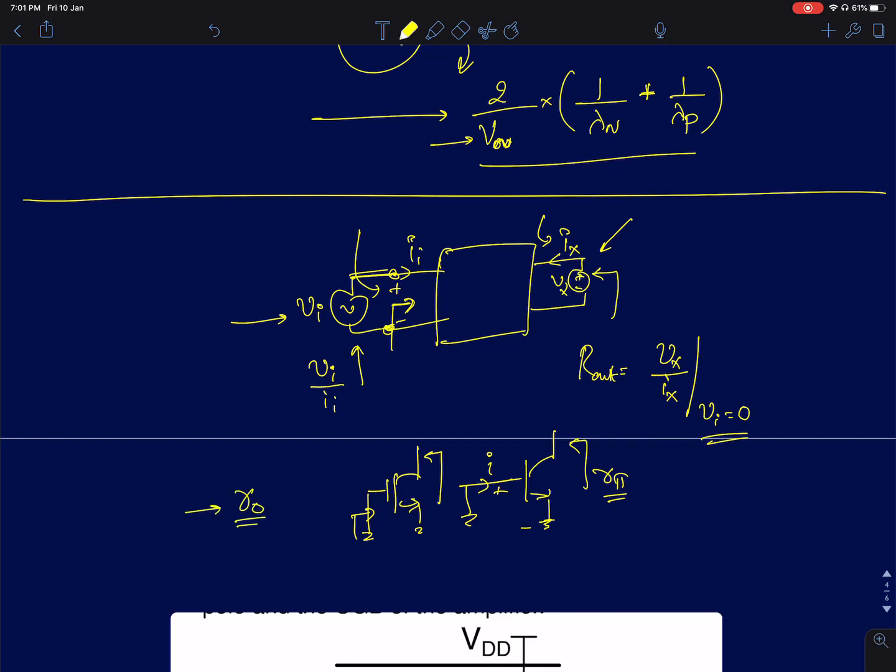Okay. So on ro, if you increase the drain current, ro is going to reduce. In a MOSFET, ro also has a dependence on the channel length. So increase the channel length and you will see an improvement in the output resistance ro. Okay. So this is it about common source configuration. Most of you, if you have taken a circuits course, by now know all these things.